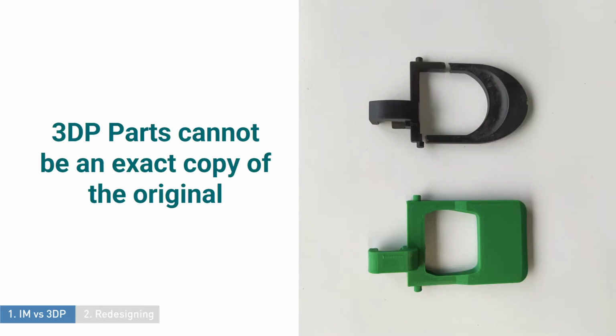The most important thing to know before we start is this: you cannot make an exact copy of the original part and 3D print it. The original part was made with a different manufacturing method, so a direct 3D printed version will not have the same properties and strength. Therefore, you will have to think how to optimize your part for 3D printing.